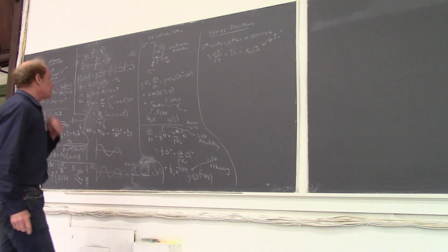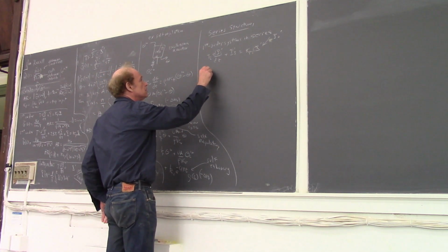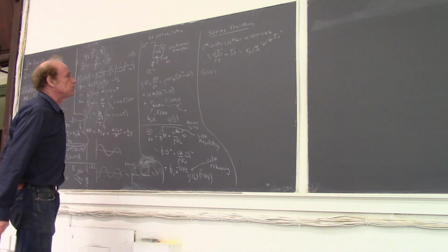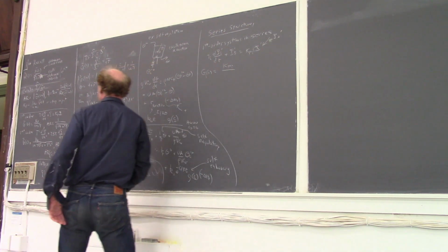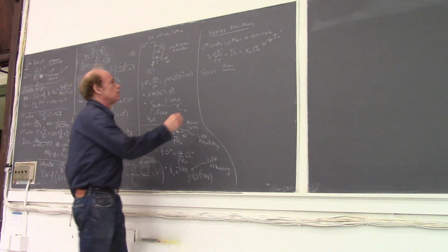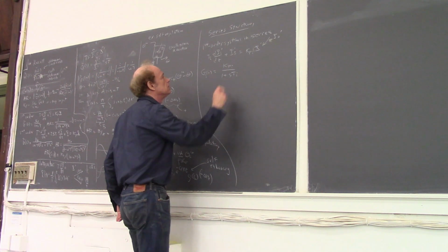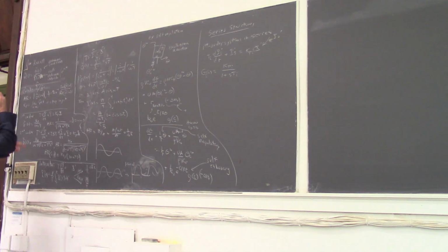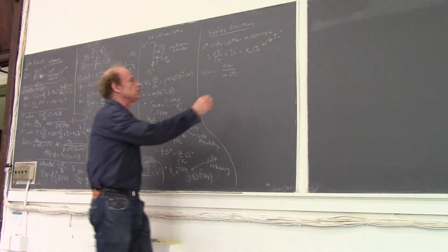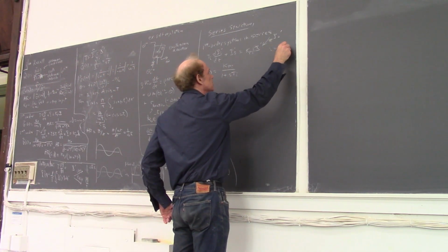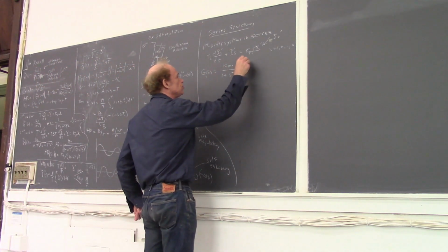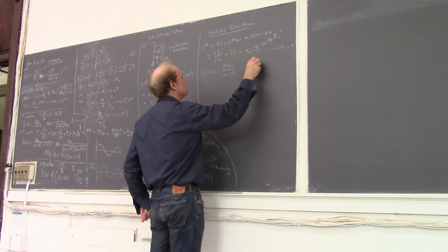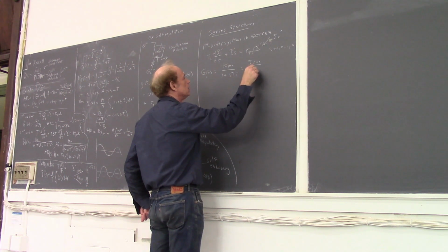We have from that g prime, g of s, which I already did. That's equal to Kpi over 1 plus sτi, by the same algebra that I did here. Going from here to here, all I did was stick i's on it. So here, i is equal to 1 to n, for n systems in series. And remember, this is equal to yi plus 1 over yi.